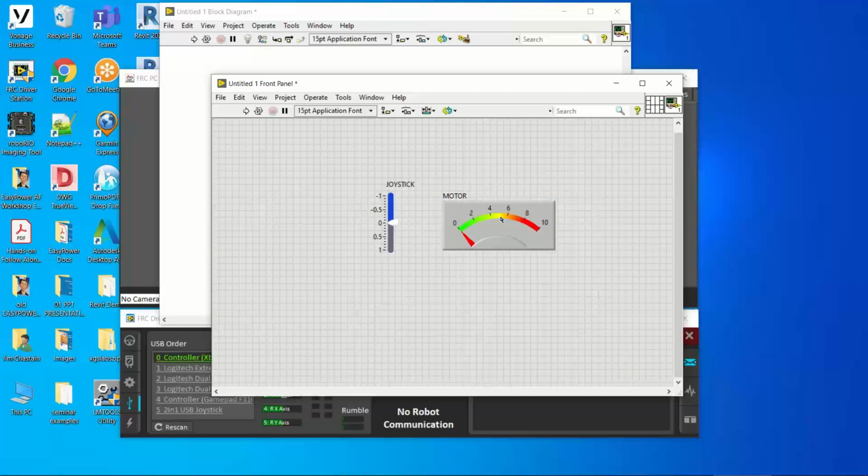the motor is a linear output device. Again, I'm going to double click on the 10 and make this a -1. We're going full speed forward. We're giving the motor a -1 signal. And then double click on the 0 and make it a +1.